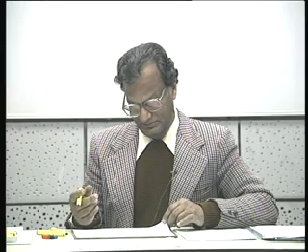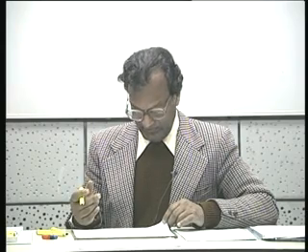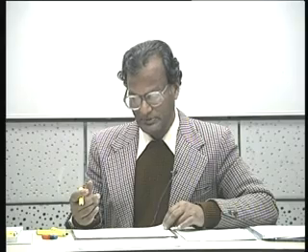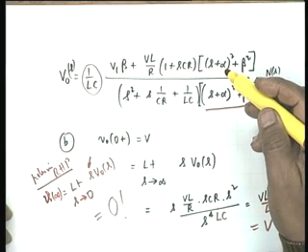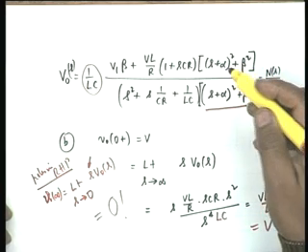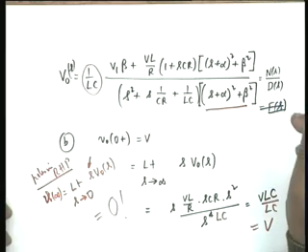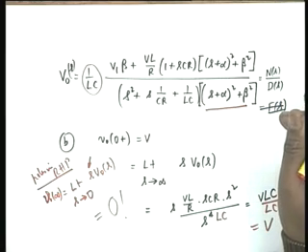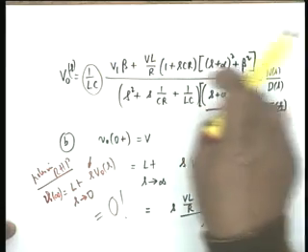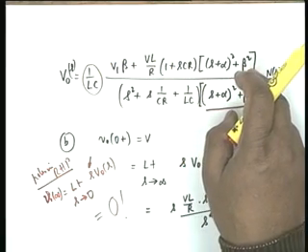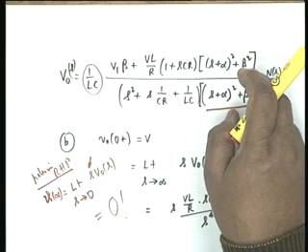Is that okay? Can we directly say that when we solve for it, we see that the power of S in numerator and denominator are the same? So can we directly say this? The power of S in numerator and denominator are not the same. This is 3 and this is 4. So when you multiply by S, the power of S shall determine the behavior at infinity, not at 0. At 0 it is the lowest power term, and the lowest power term, when we multiply this by S, obviously contains an S, and therefore when S goes to 0, it is 0.